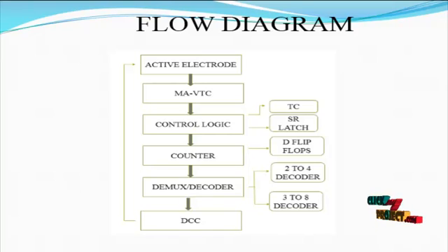From this point on in the circuit, the signal information is in the phase of the VTC output signal. The output of the VTC is applied to the time mode processing block, in which the anti-aliasing and offset cancellation are done in time domain. Then a time to digital converter transfers the time mode signal into digital domain, where other processes such as digital filtering, data compression are performed.